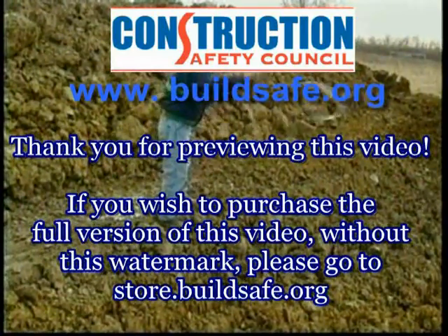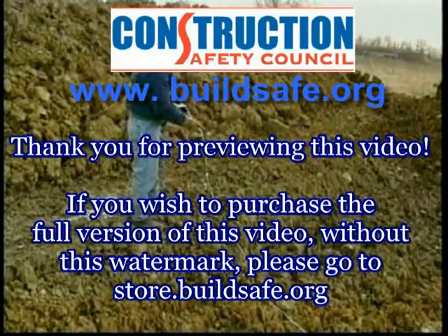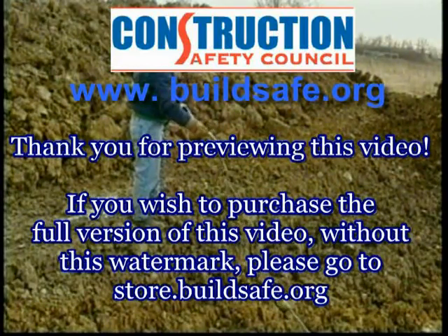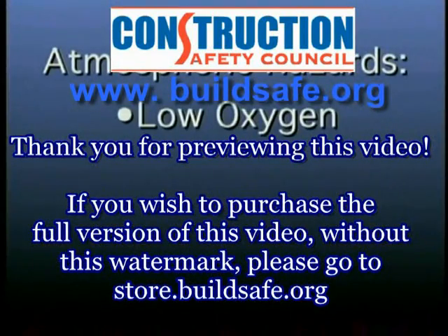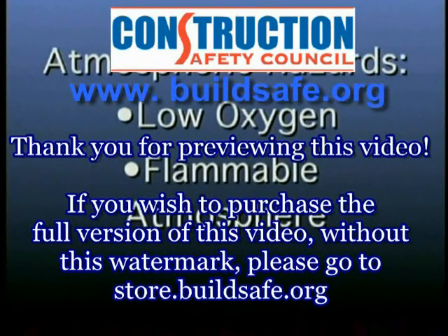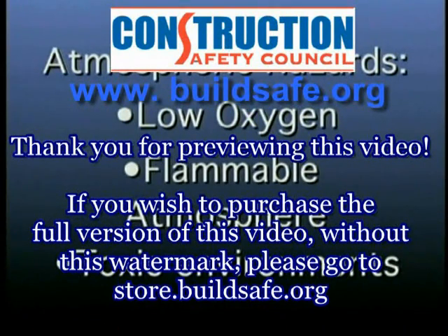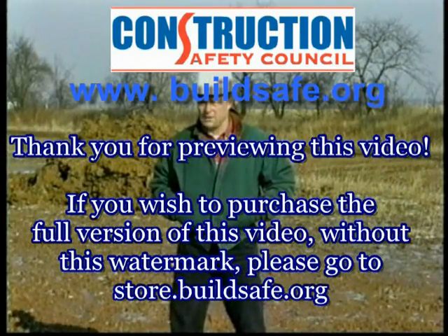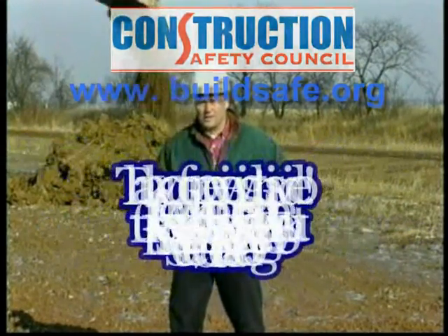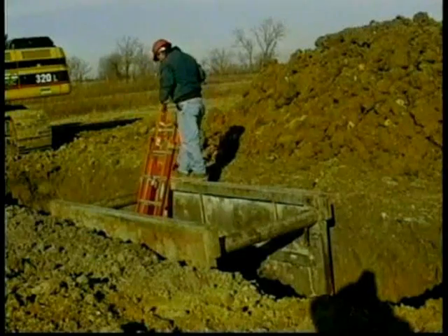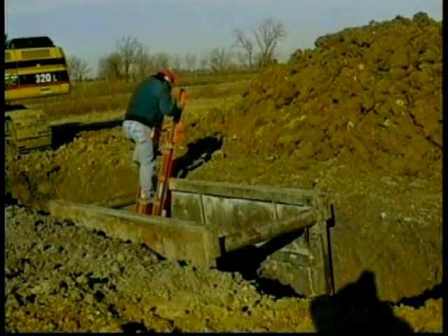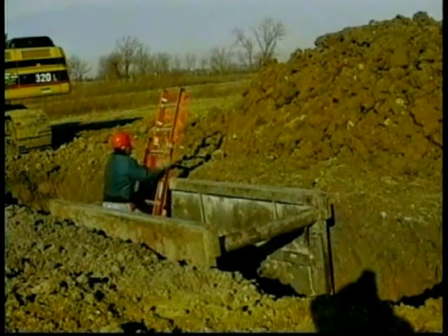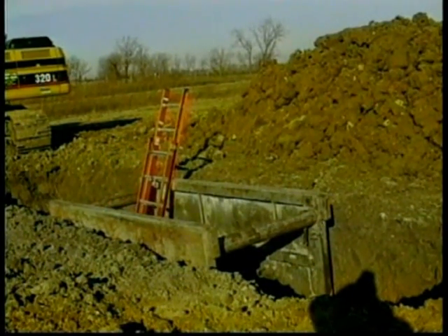The competent person needs to examine the excavation for hazardous atmospheres. Primary atmospheric hazards include low oxygen levels, a flammable atmosphere, and toxic environments such as carbon monoxide. Some causes of these hazards include nearby utilities like sewers that contain gas or liquids, and nearby landfills or swamps can create dangerous atmospheric conditions, in addition to nearby traffic. When the competent person determines that the atmosphere in the excavation is not hazardous, then work inside it can begin.